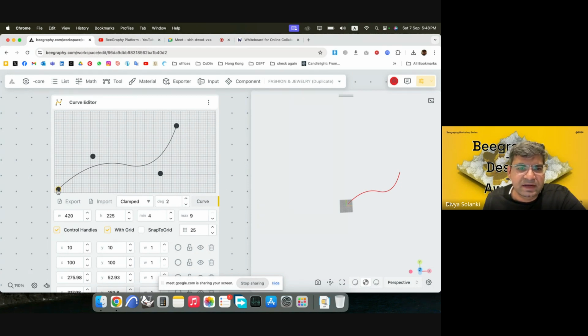It's an 18 by 9 grid, which is based on this 420 by 225. So if I take one of these control points to say the middle of this grid, it would come somewhere here, which is 210, 110. So that would be my base point from where I would move this geometry and take it up to the mannequin.